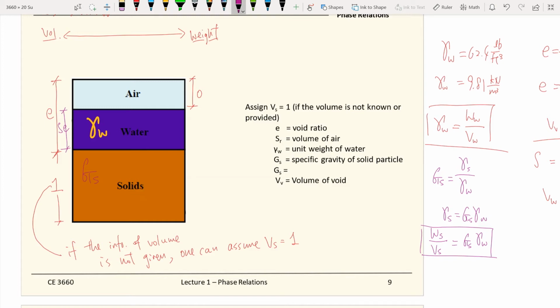And the total volume, you can also visualize on this graph, is 1 plus the void ratio. This gives you the total volume. So we are getting there. The purpose here is to represent the whole phase diagram with the terminology that we have learned. For assignment one and for this lecture, this is a prerequisite, but that's okay. If you can understand this slide, that means you are more than ready for solving the homework problems and exam problems.